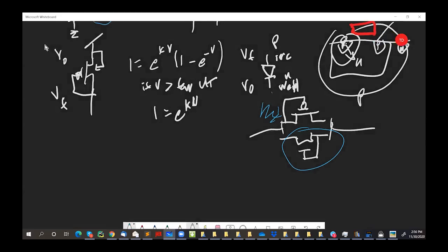Okay, so I think I'm going to start with the so-called cascode. It's called a cascode because of the days of tube electronics, because this particular shield in between the plates in a vacuum tube device was called a cascode. I don't know why somebody came up with that name a long time ago. But as I said, it's kind of a shield. I'll explain why it's a bit of a shield and how it deals with the Miller effect.